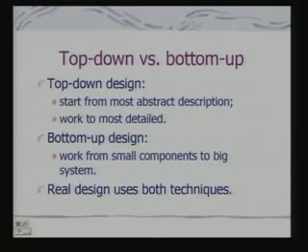The design approaches can be top down or bottom up, just like any software design. Here also this issue comes up. In a top down design, you start from the most abstract description and work down to the most detailed level. The bottom up design, which is also very common in embedded system design strategies, you work from small components to big system. Because in many cases, when somebody is developing a product, you have got parts of it already developed, maybe some components from a previous system, and you would like to use those components. So, you try to go through a bottom up process, and in fact, any real design actually involves both.